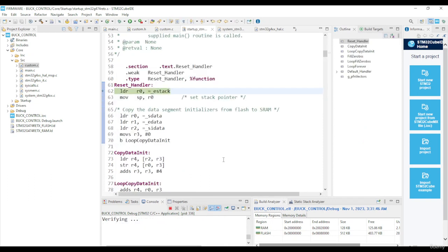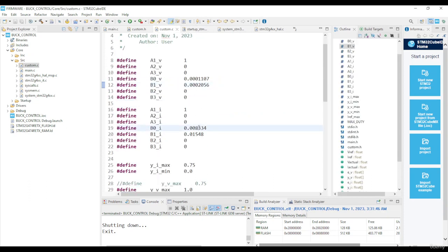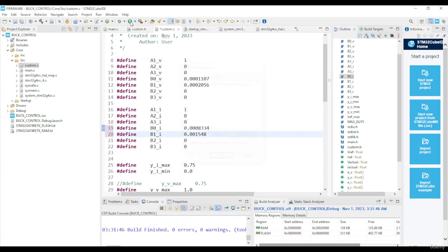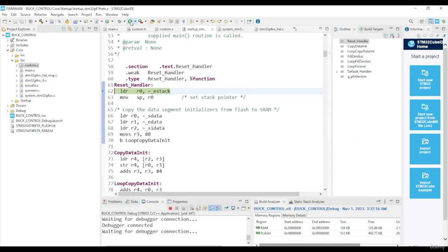Okay, let's run. I just checked it over there. I think it would help to have this like that as well. To reduce it, essentially what you're doing is you're increasing the settling time. When you make the coefficients much smaller than what you actually calculated, you're reducing the settling time, and you actually have a much more stable output.